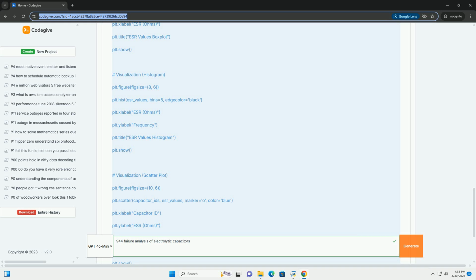Capacitance meter, accurate measurement. A capacitance meter or LCR meter provides a direct reading of the capacitor's capacitance value. Compare the measured value to the capacitor's rated capacitance and tolerance, usually printed on the capacitor body. A significant deviation from the rated value indicates a problem.